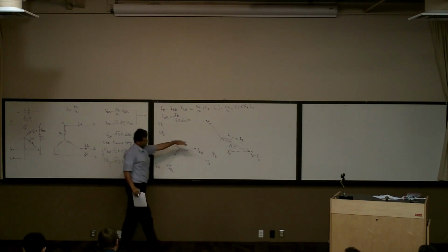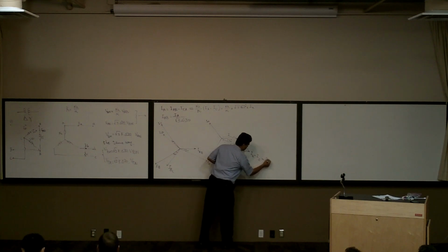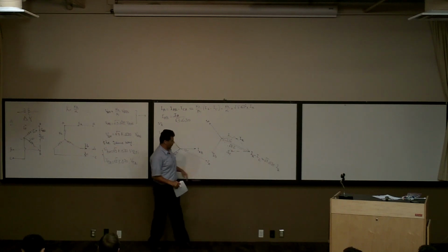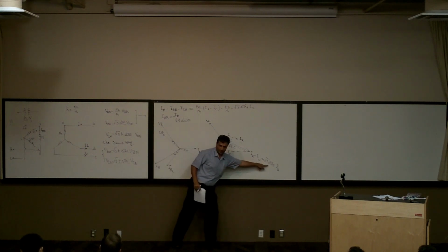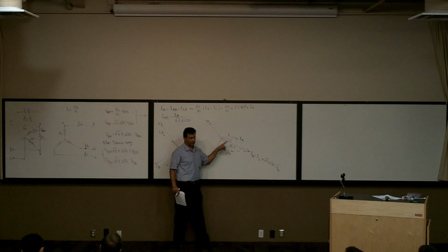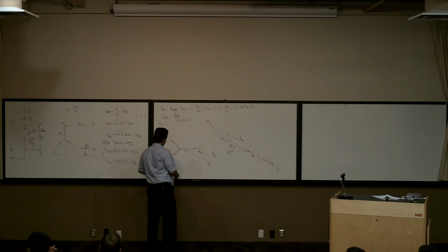So, this is the IA, I'm going to write it here. This one is equal to the square root of 3 with a minus 30 degree times I. So, look at this vector, it is 30 degrees behind, right? And times square root of 3 is going to be this. So now, we find this one.